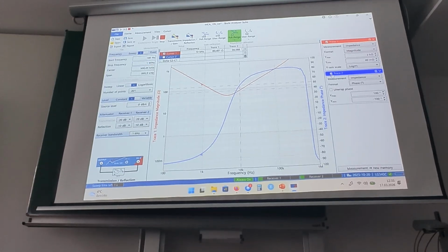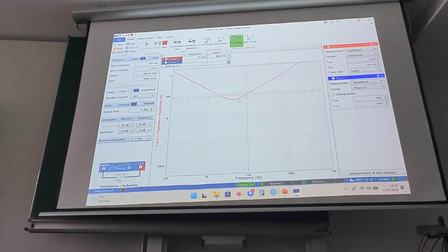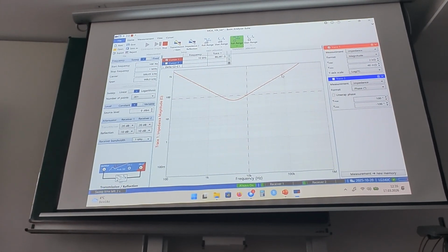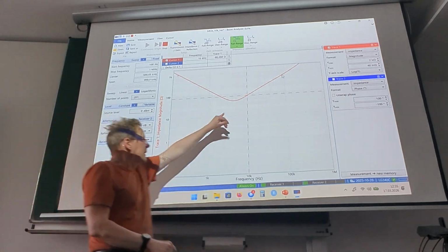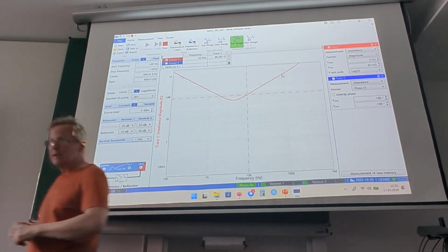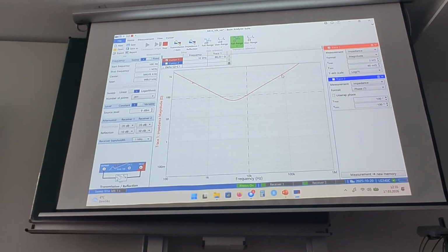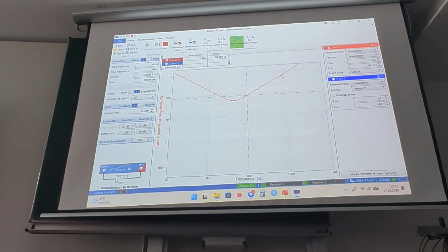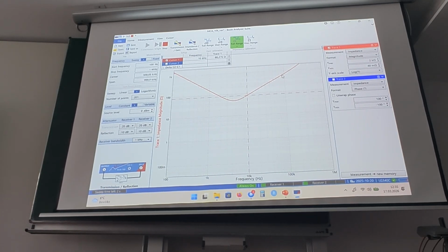Sorry, this is a bit confusing. Okay, so this is just the resistance as such. Well, it rises now because the coil, the inductivity, has an increasing impedance, so it does not want the change, you could say. It produces a high voltage if you try to change the current very fast, and that means it has again a high impedance.